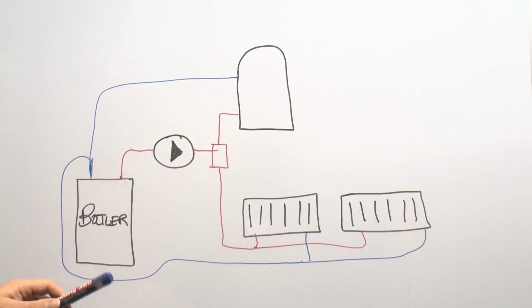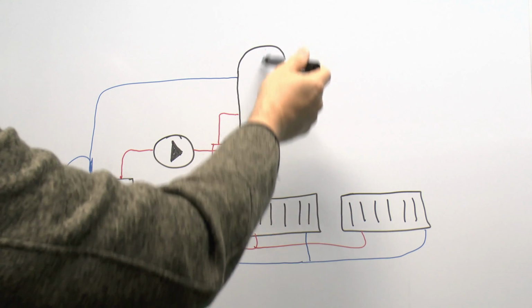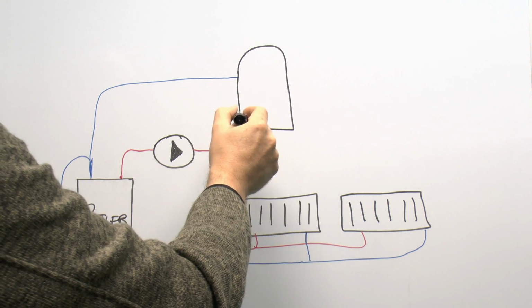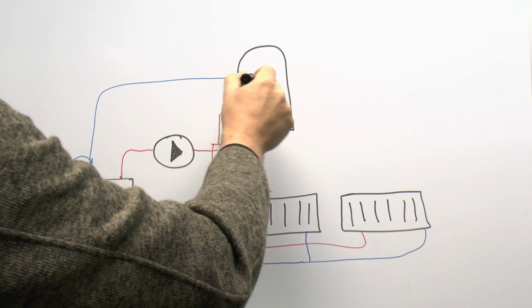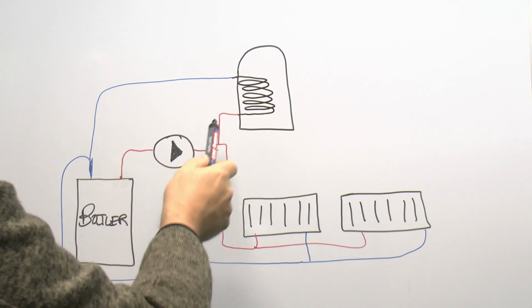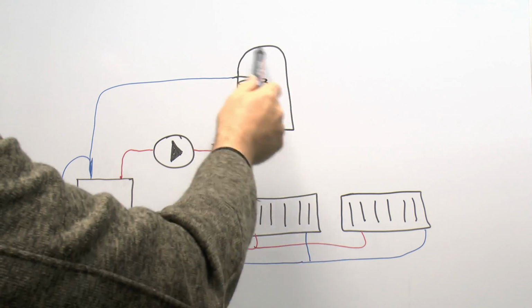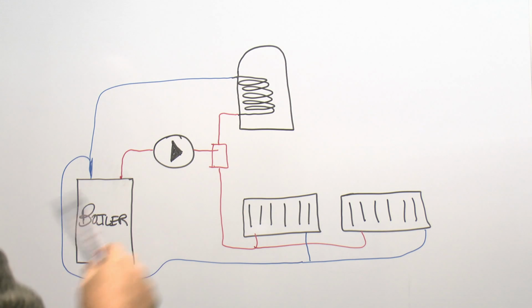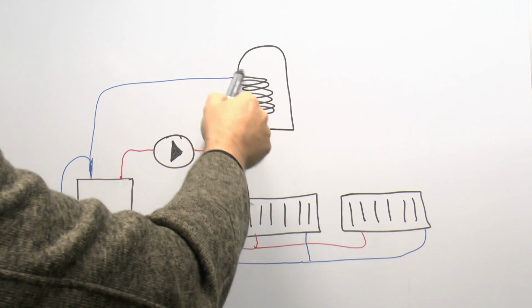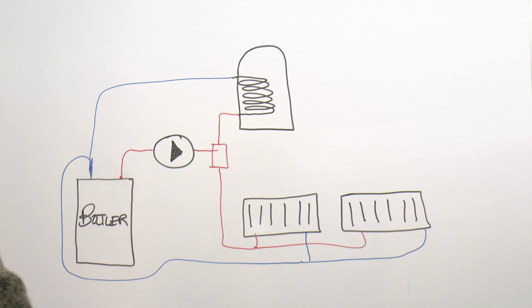And the hot water cylinder is a fairly straightforward device. Basically it's filled with water, and then inside is a coil of copper piping, and as hot water is circulated through, then it heats the water contained in the cylinder. And the water in the cylinder is what comes out of your hot taps. The two types of water, either in the cylinder and the coil, are two totally separate systems, and one does not ever mix with the other.